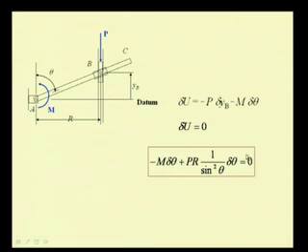So, from this equation we can now remove this delta theta, because virtual displacement is not 0. So, the other term has to be 0, and from that we get the relation between the applied moment and the force. So, if we know the distance r and this configuration theta, we can find this value of M with respect to this force P.